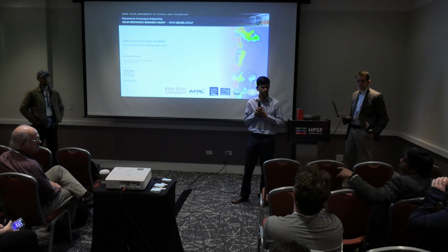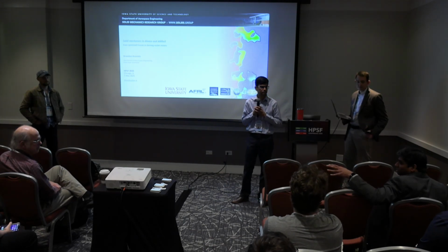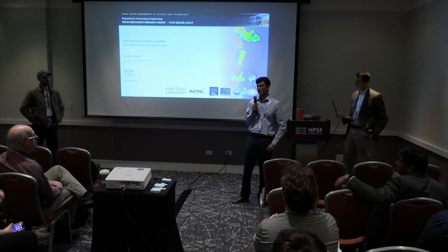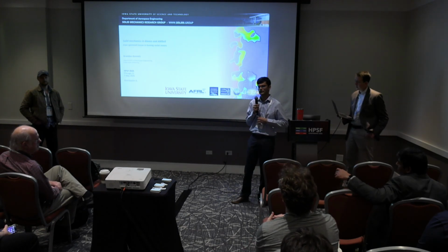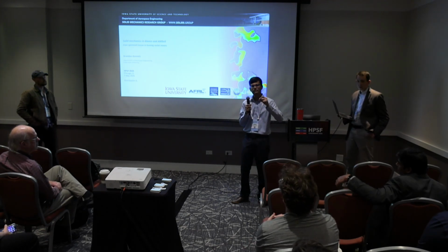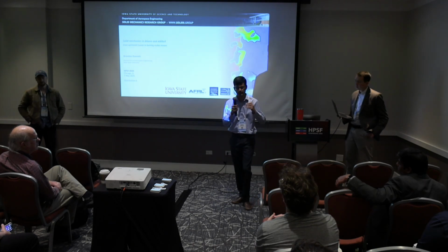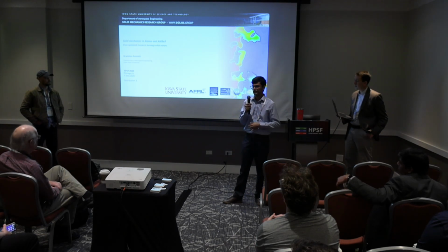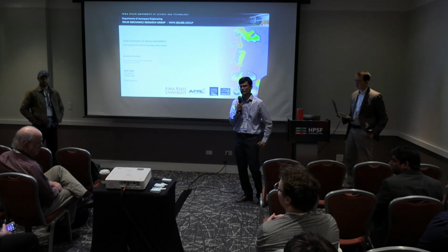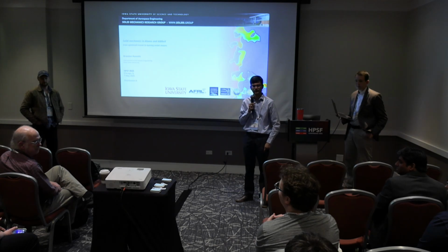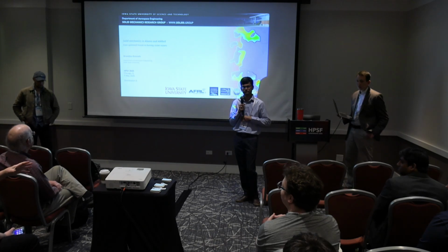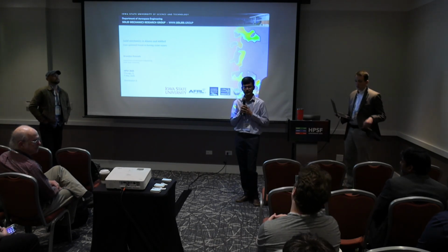Exactly. I think the question is more, if there is the SRD correction, the small cell fix, then why do you do that at all? I think this is a filter. The very small cells, we just don't want the fluid solver to see. It makes the fluid solver stiff in a different way than what SRD addresses. In theory, SRD takes care of it all, but the reality is that 10 to the minus 7 cells are not really what's computed. There's a sweet spot where SRD is good, but you might as well get rid of the really small ones.